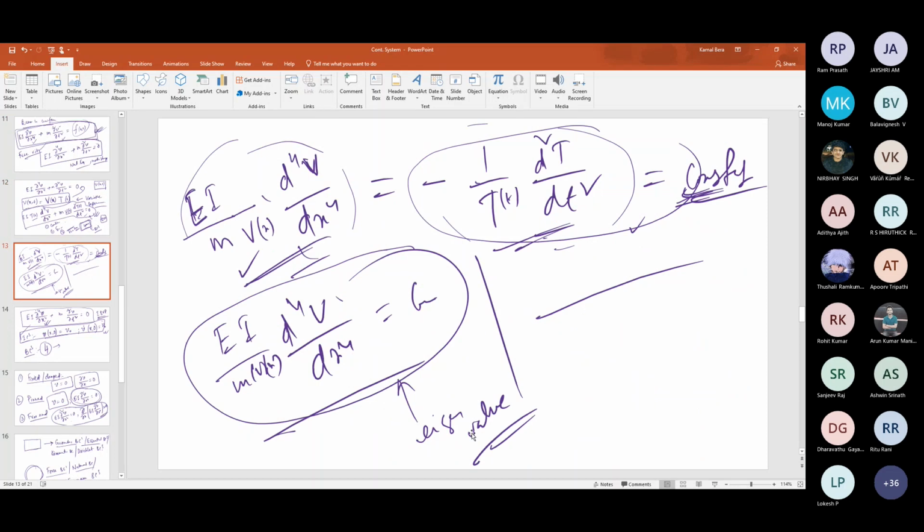The space related will give me the eigenvalue problem. I will use the appropriate boundary conditions to get the frequency equation or the characteristic equation. Solving that, I will get the frequency and the mode shapes. Here it is eigenvalues and eigenfunctions, not eigenvectors, because it is a function of x. And then the time dependent part is already known to us. That will give you the harmonic solution. Synchronous motion, time dependency is harmonic. Okay, so I'll stop it. Any doubt with today's discussion so far?